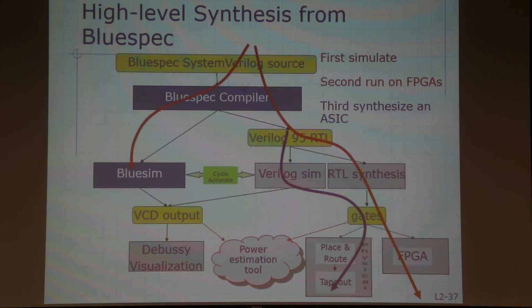So for example, when we are doing simple circuits, this is good enough, right? And you could go directly to ASICs or whatever. But when we are doing things like microprocessors, then at some level, this thing runs out of oomph. It takes so long to boot Linux on an out-of-order processor in simulation mode that you say, oh man, how do I? And it runs 70 million instructions, and something is not right.